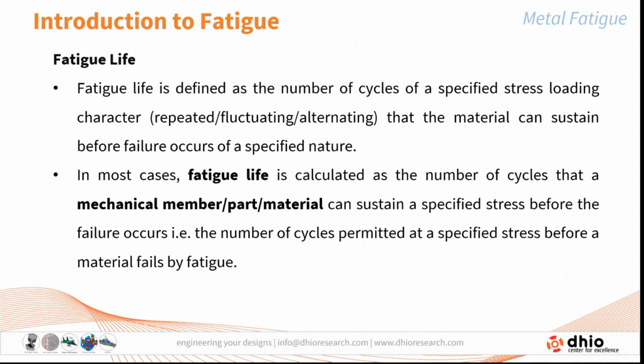Now, fatigue life is defined as the number of cycles of a specified stress loading character. It may be repeated, fluctuating, or alternating. But for the standard data which are available for different materials, the fatigue life is based on the alternating cyclic load that the material can sustain before failure occurs at a specified nature.